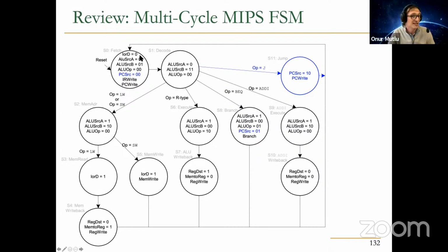Now you can optimize each state, how long each state takes. You can break one state into multiple different states, increase your clock frequency or reduce your clock cycle time. You can figure out a better way of executing the instructions by having it go through fewer states.